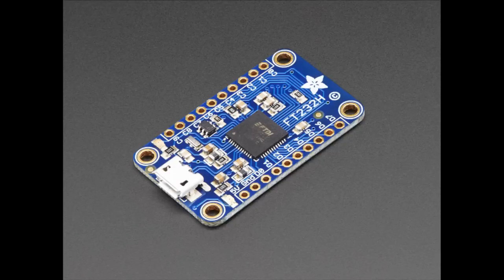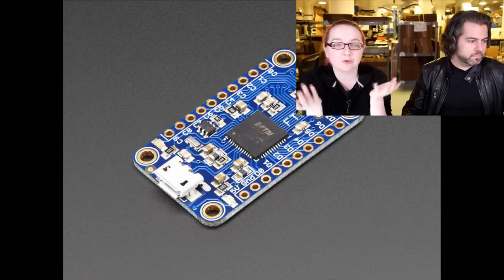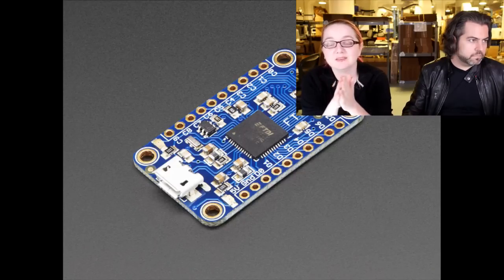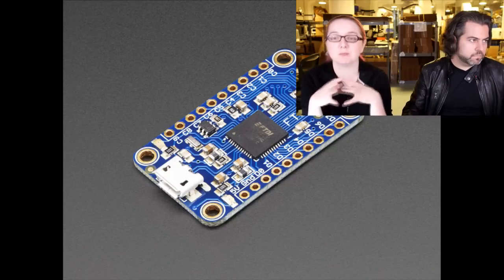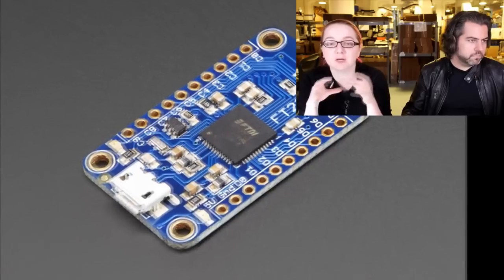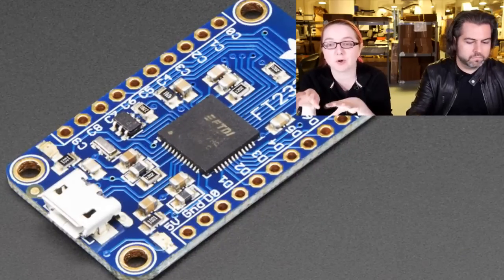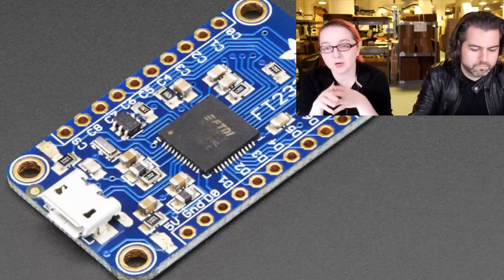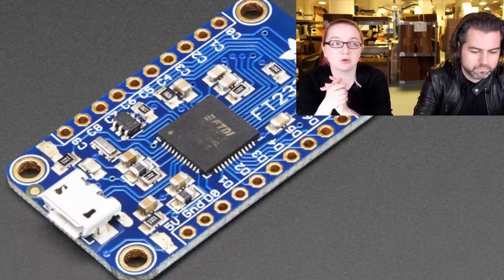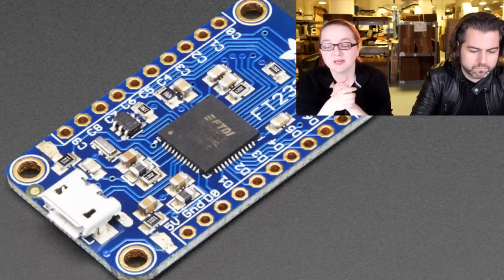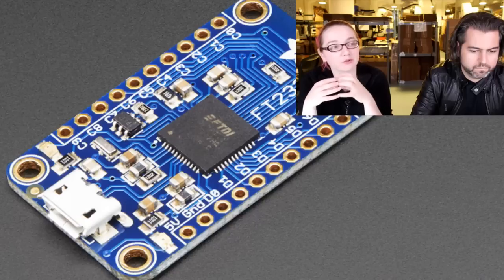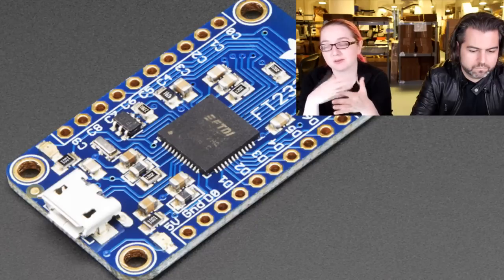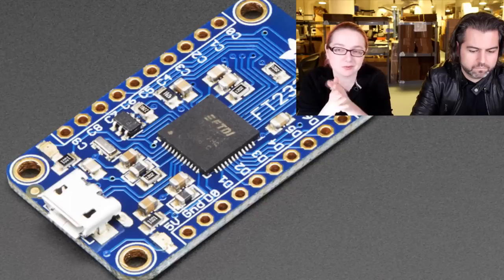It's a chip from FTDI, and it sounds like the FT232RL or B, which you may be familiar with, the USB to UART chip. This is kind of similar, but it's even more so. Instead of just doing USB to UART, it does USB to UART, but it can also do SPI, I2C, and just basic GPIO. It's 3 and 5 volt compatible, so you can use it with just about anything. And it's what we think of as a really good glue logic chip, because you can use Python. There are Python libraries for it, and there are also C and C++ libraries. We like to use Python.